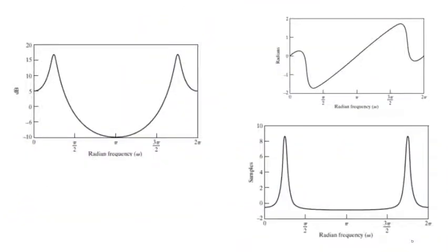On this slide we have a graph for the example we considered on the previous slide, which consists of two poles and two zeros. For the magnitude response or the frequency response for this system, that is a complex conjugate pair of poles, making r equals 0.9 and theta equals pi by 4, we have this plot.